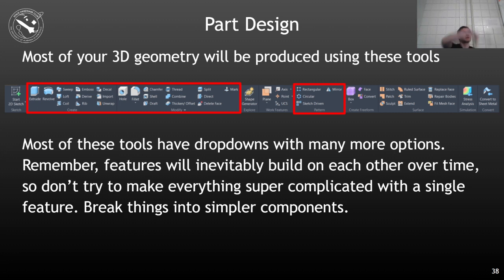There's also the loft tool that you can use, like with the traffic cone thing. You can have a sequence of different shapes that you are then dragging all together to make this kind of stitched thing. Think of it like making tunnels or something. You can tell by the image right here. You can have some square profile and then some circular thing at the top, and as you go from the square up to the circle above it, it's changing the geometry as it goes and morphs up to the top of it. On the traffic cone, you can have a big circle at the bottom, and then it morphs into a smaller circle at the top. That's one way that you can use that.